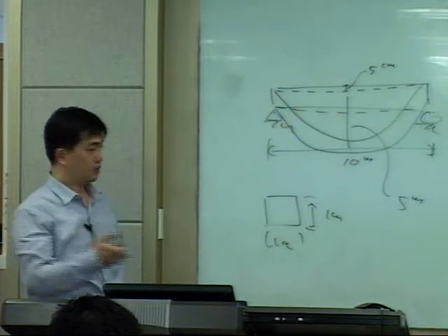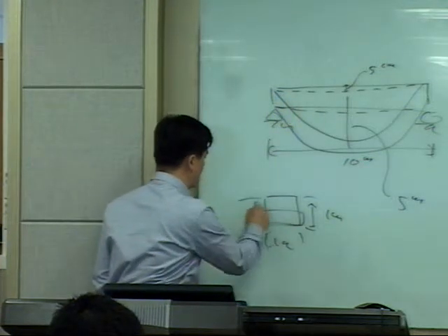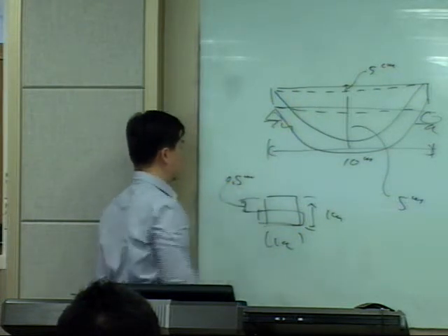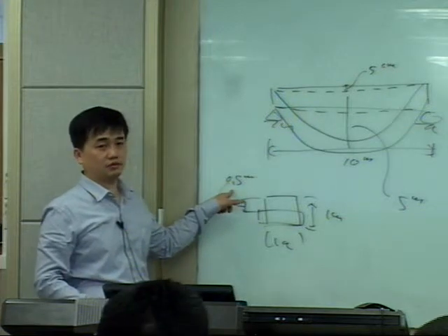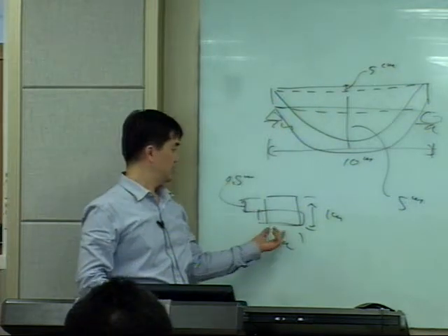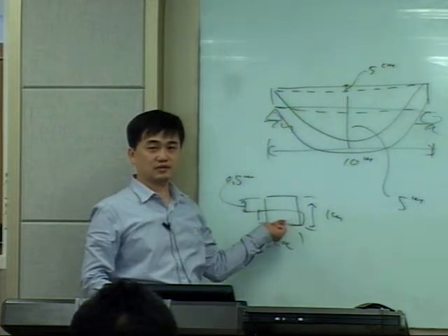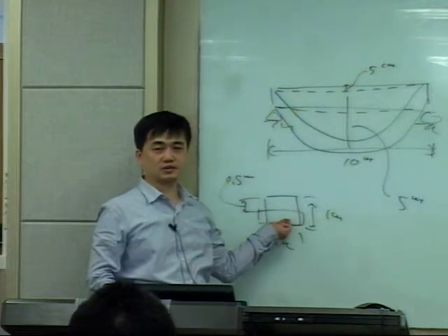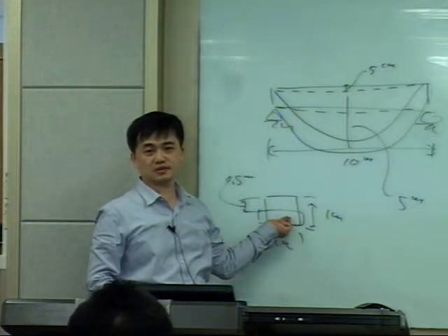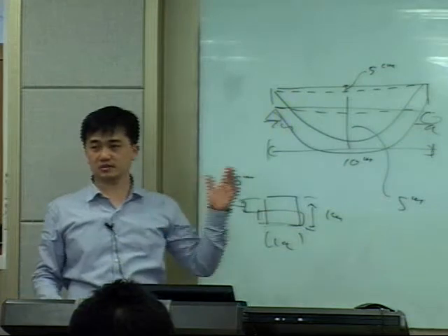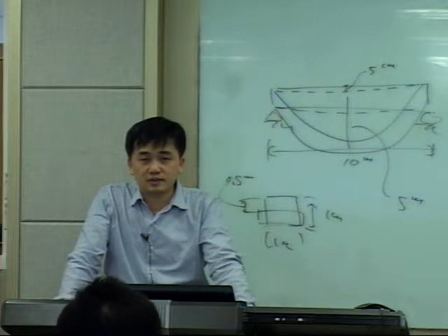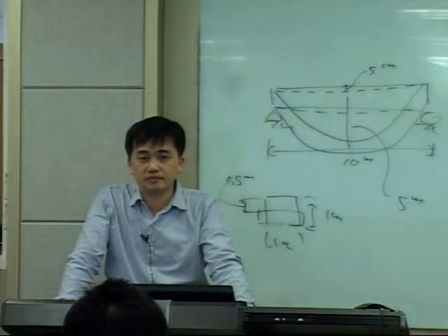You can make it deform 5.5 centimeters. Even though the absolute value of deformation is much smaller than in the previous case, the overall length or scale of this dimension is very small, so this is a large deformation. So the concepts of large deformation, large strain, and small strain depend on the scale of the problem.